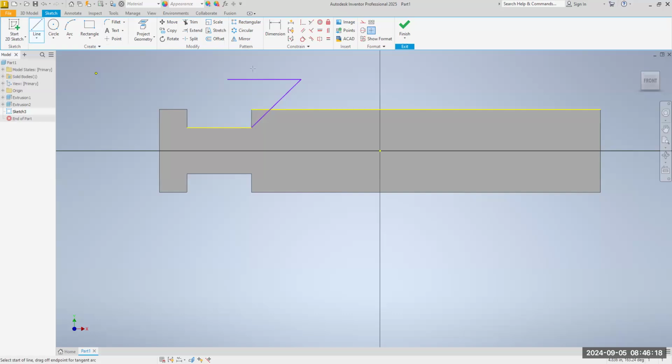Make sure you go straight up. You got to go straight up. Left click, right click. Okay. Then I trim it. I don't care how big this triangle is, but I do care about the angle. I do care about the angle it makes right here. And I'm going to change that to 60 degrees. Select the green check mark. Yay, that's what I want.